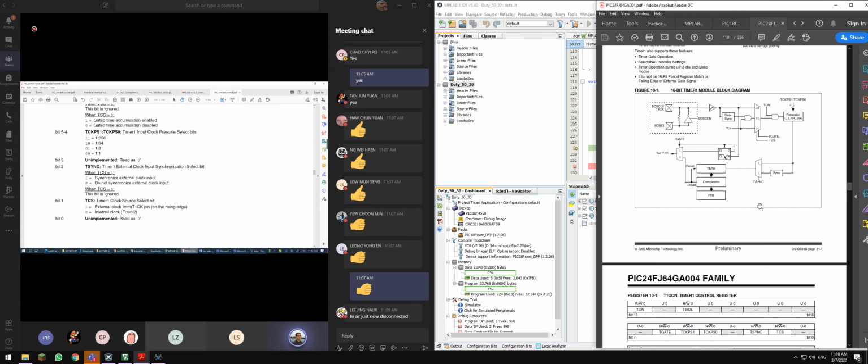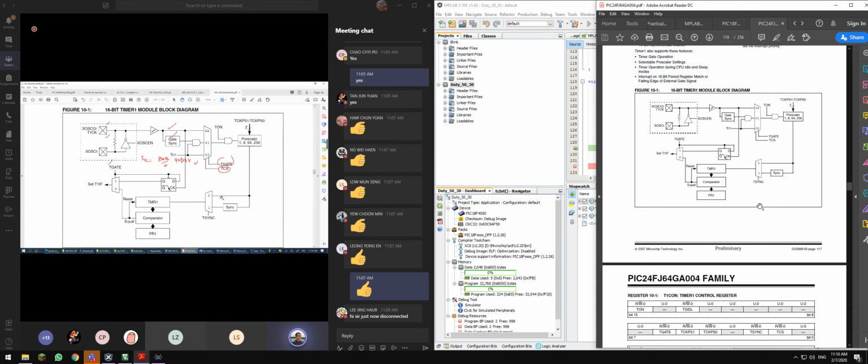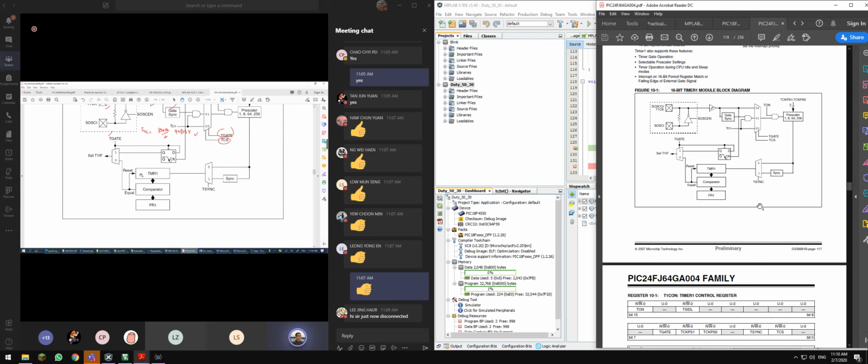1 means that, as I told you just now, you want to detect the number of people going into the library. Every time someone goes into the library, it automatically increments TMR1. TMR1 will be incremented. And remember this is 16-bit. It's not 8-bit, because this is a 16-bit microcontroller.